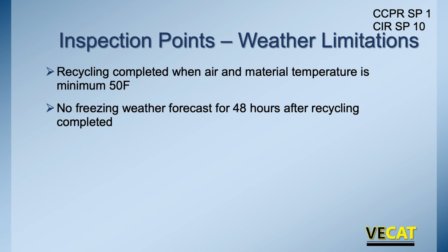Talk weather. Whether it's cold in place or cold plant recycle, it doesn't matter. The weather limitations are the same. Recycling is completed when the air and the material temps are 50 degrees minimum. So we're looking at 50 degrees and higher. We're not doing this in the 40s. We're not doing this in the 30s. We have found through experience it does not work well. So that 50 degrees is in the spec for a reason. And we don't want any freezing temperatures forecast. Reason being, both whether it's cold in place or cold plant, we're injecting an amount of water. If that water hasn't evaporated before it freezes, water freezes, it expands, and it can break down the bonds.